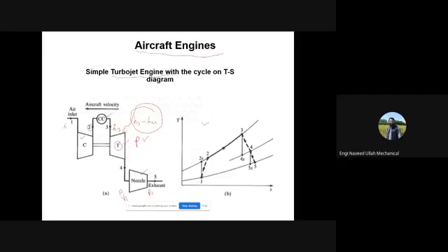will be having pressure P2 and velocity V2, and the exit velocity or the jet velocity will be greater than V1. Why? Because the shape of this duct is responsible to increase the velocity and decrease the pressure, right? So this is basically the higher the velocity of jet leaving the nozzle, as a result and as a reaction, thrust will be produced in the forward direction, which will give some velocity to the aircraft, and that is basically your thrust.